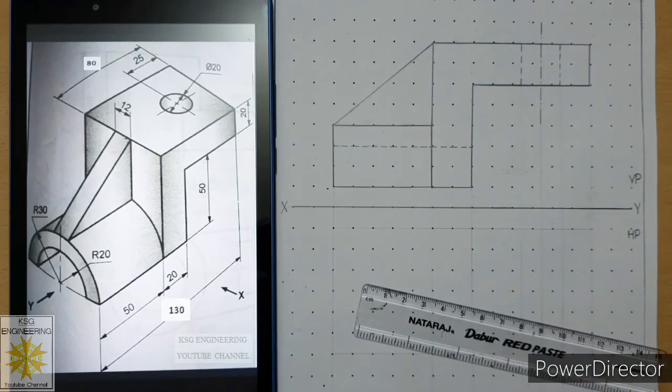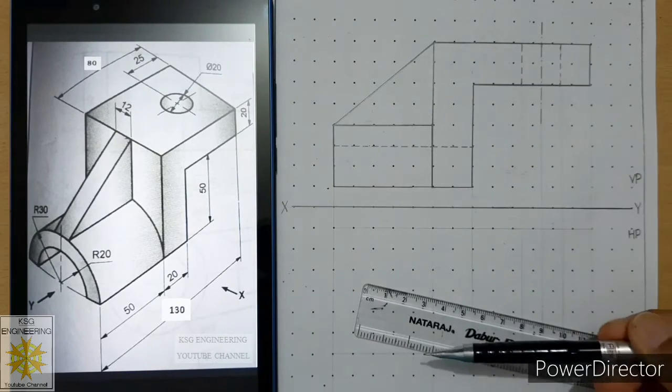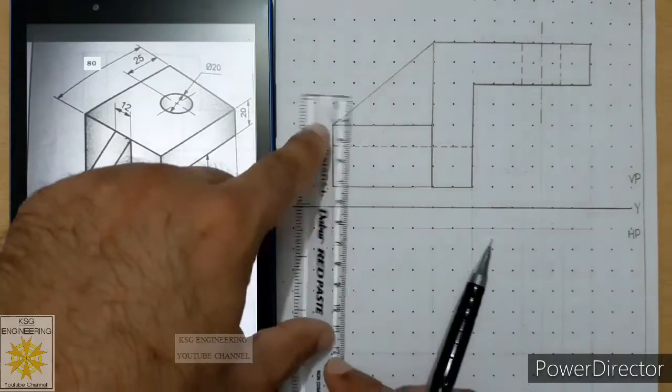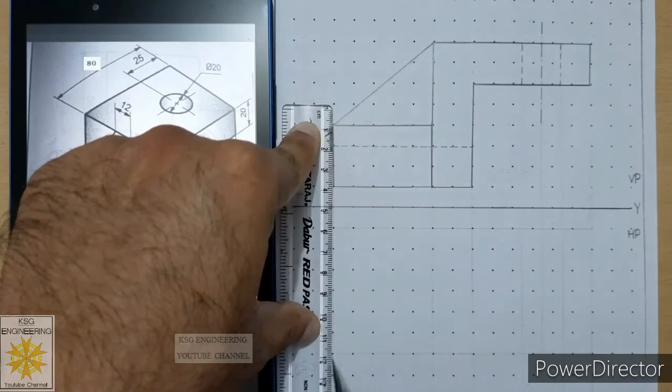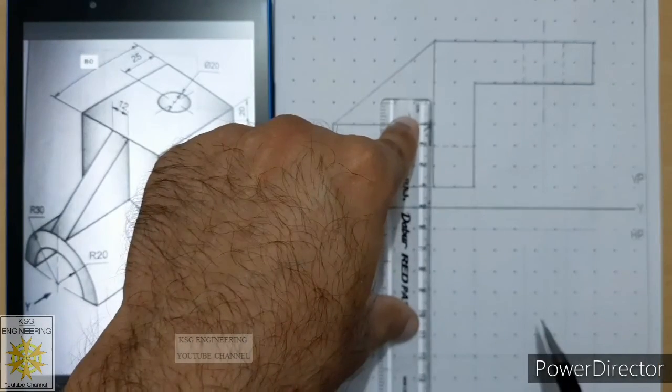Now we are ready with the front view of this object. What is the next step? We have to draw projectors from all the points of the front view in downward direction. So for that we have to line our scale with this edge first, draw a continuous thin line, then align with this